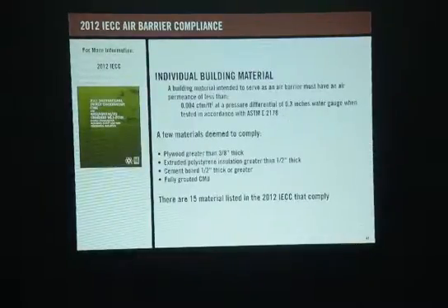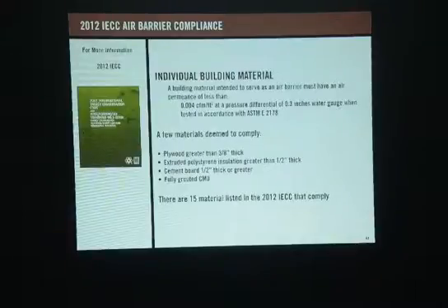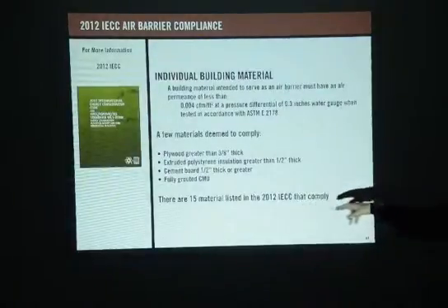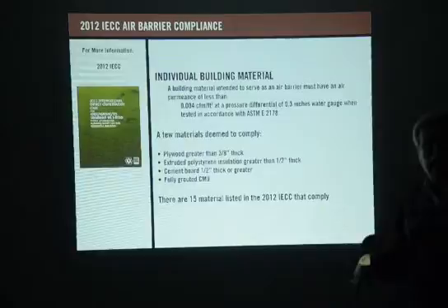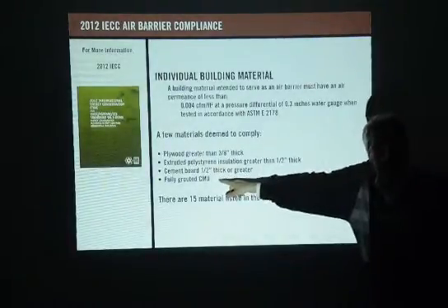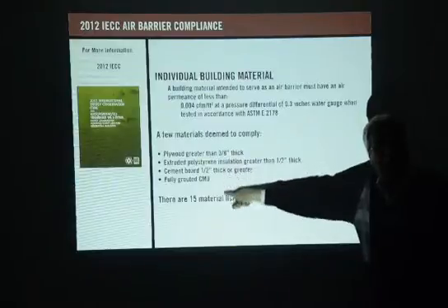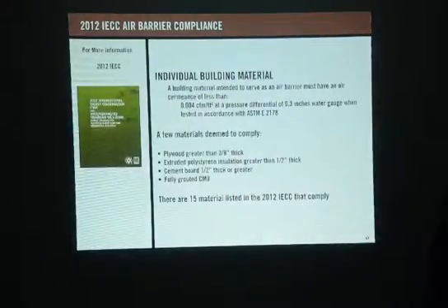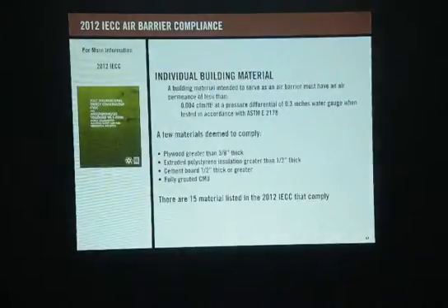This is before assembly of the wall, right? Yes, this is just for the one block. Correct, testing on one block, not on the whole thing. That's correct. Good point. We mentioned 15 different building materials in the 2012 IECC code, okay? Look what's in there. This is one of the 4, but it's actually 15. Fully grouted CMU, okay? Compliance, right there, bang.